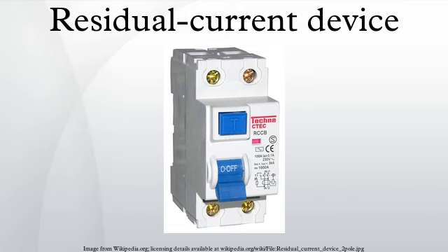European installations continue to use primarily RCDs installed at the distribution board, which provides protection in case of damage to fixed wiring. In Europe, socket-based RCDs are primarily used for retrofitting. Regulation and adoption: regulations differ widely from country to country. In most countries, not all circuits in a home are protected by RCDs. If a single RCD is installed for an entire electrical installation, any fault may cut all power to the premises.